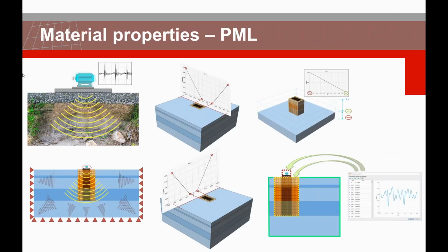Another landmark development that we offer in 10.1 is the PML method, the perfectly matched layer method. This method is intended for absorbing the energies or the waves that are propagating in our medium. So imagine we have machinery operating on the top surface on a solid foundation, and by vibration of this you can see the signal and waves are propagating in the soil.